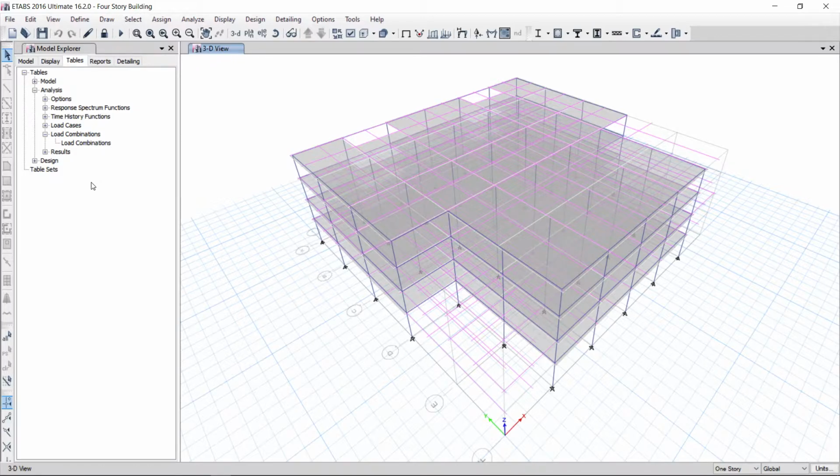So I can say that although it is a little bit conservative, it is not actual as per the codes and standards. What I can infer from here is that in the load combinations generated automatically by the software, they have ignored this condition. Why they have ignored it, I do not know.